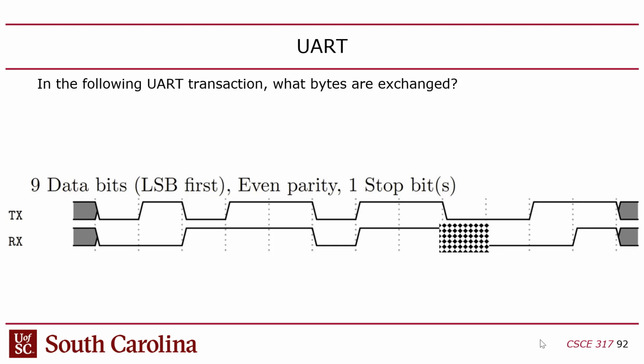However, if you know which bit is an error, then it becomes what's called an erasure, in error correction coding. An erasure is where you know that there's an error, and you know the position of the error, and you can use the parity to actually fix the error. You can correct it. Now, do you normally know where the error is if you get an error in a UART channel? No, I don't think so, unless you have a receiver that can measure noise margins or something, to detect that there was an error.